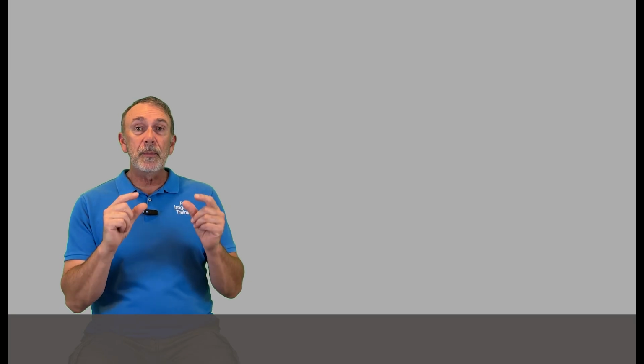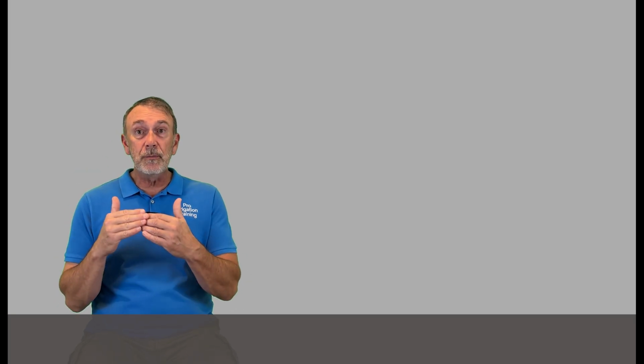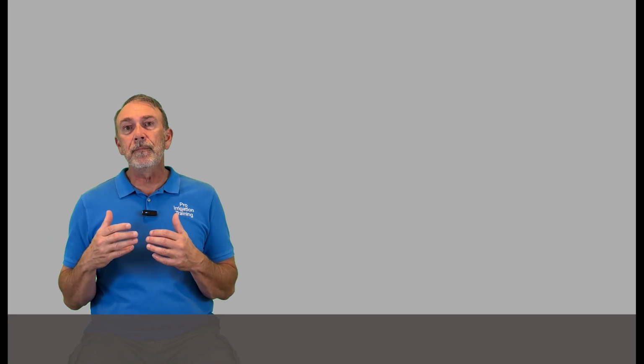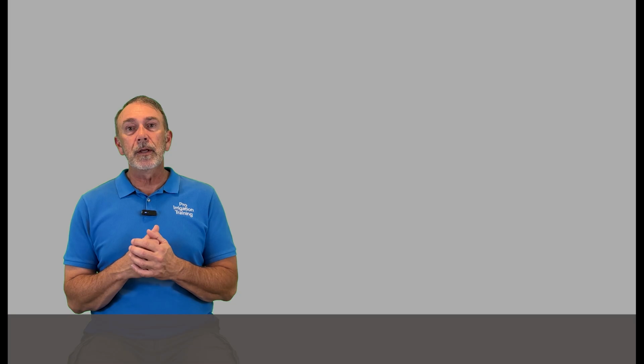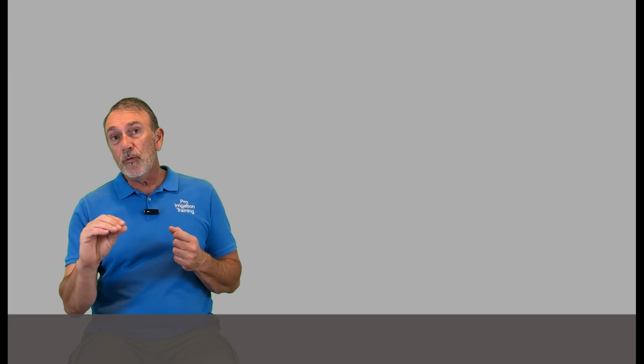So if we've got 6 heads, it's doing a good job of meeting that demand. But if we add 2 more heads to it, pressure wants to meet that demand of that extra flow that we're asking from the system by adding 2 more heads to it. Well, the only way that pressure can do that is by increasing the speed of the water moving through the pipe.